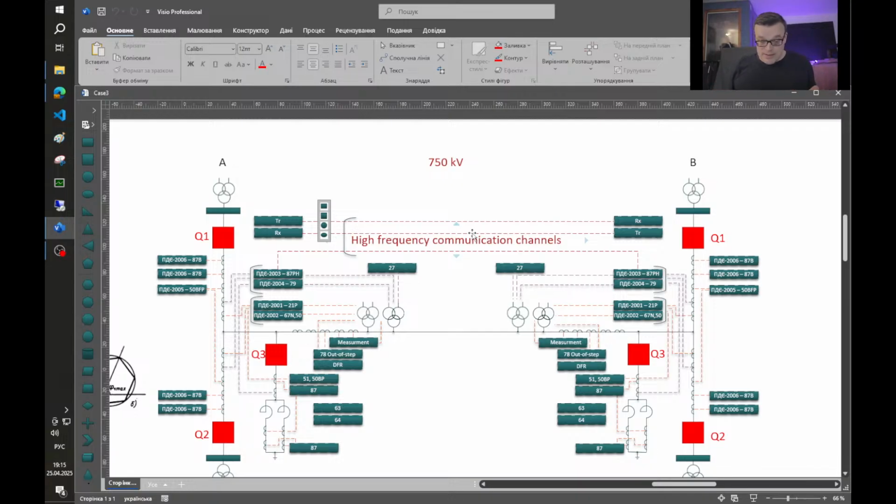in Ukraine, system integrity protection is a whole universe, and it's signals transmitted not just between two substations, but they can come from one part of the country and go to another part of the country, and there trip 200 megawatts of load.